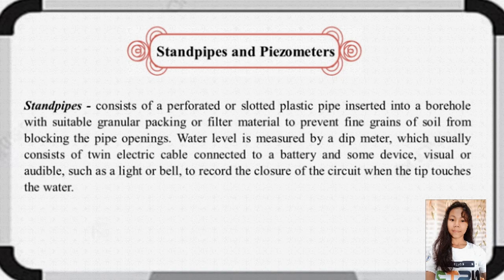Fortunately, the first disadvantage may be overcome by using a piezometer. Standpipes are used to locate the water table, and the second disadvantage is reduced by using a small diameter pipe so that the piezometer will respond to a lower volume of water flowing into the system.